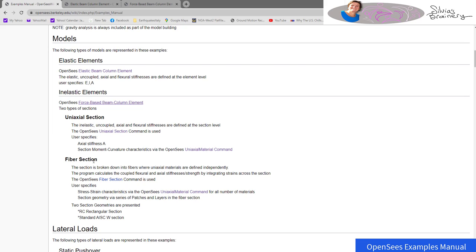So my recommendation would be to use a fiber section where you need it, where you need to model PM interaction. Now, axial force can be taken into account in how it affects the moment strength. I mean, you can define different cross sections and properties depending on whether it's a bottom column that has a lot of gravity load or a top column that isn't carrying as much weight.